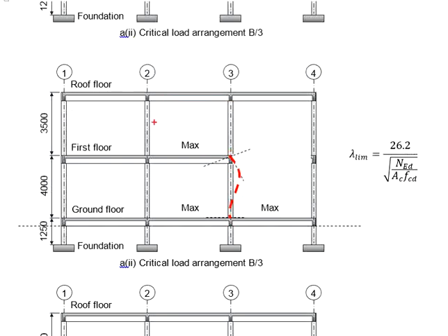Let us look into the second load setup. Again, maximum load here, both sides maximum. When the spans are the same, and when the loadings are the same, there should be no resultant moment. Without resultant moment, the axis of the joint does not rotate. Your column will still remain 90 degrees to the axis.